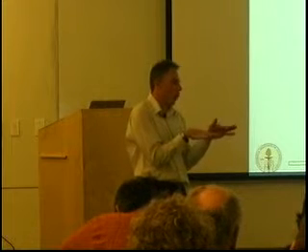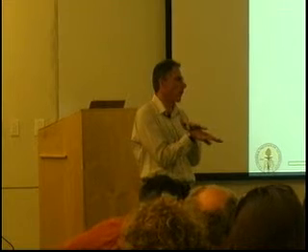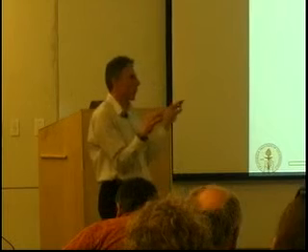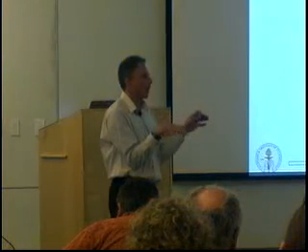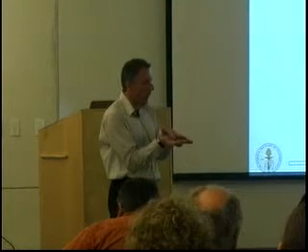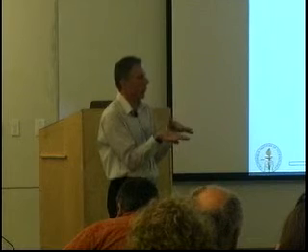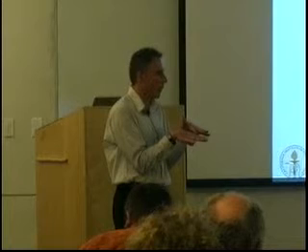So when I texture a surface, that surface itself has a different reflectance from a planar surface that has an optimal planar thin film dielectric AR coating. Okay, I can combine texture plus a dielectric AR coating to further reduce the reflectance of a surface if I choose to do that. Is that what you're getting at?